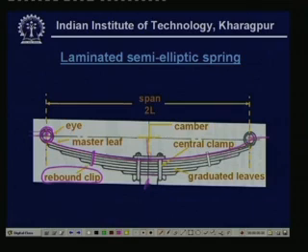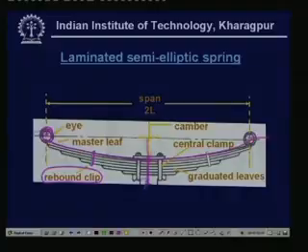And this particular one is a central clamp, and this central clamp has a central bolt to fix it up. That has some tendency to weaken the springs, but anyway, because the clamp has some width over here, that takes off the total weakening effect of this particular clamp.